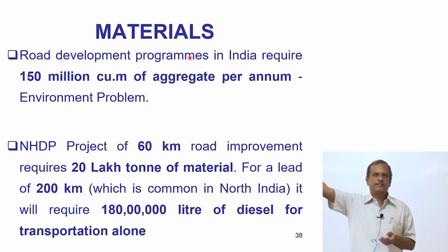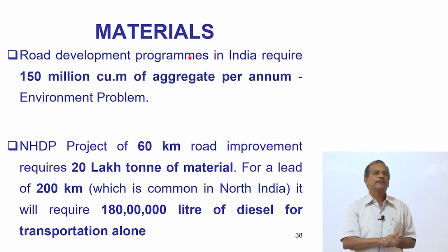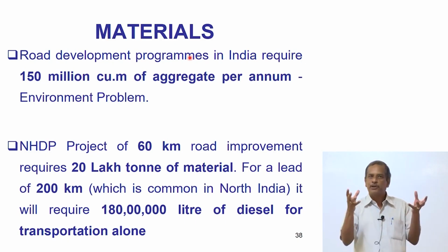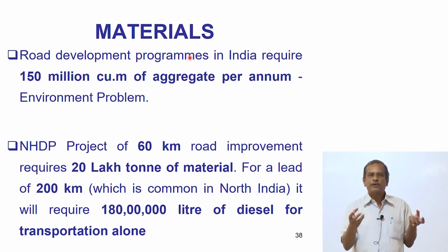If you go to the Northeast, you will not get good quality aggregates at all for road construction. If you go to the Andaman and Nicobar Islands, all the aggregates there will absorb moisture. The water absorption may be more than 2%; we permit up to 2%. If it absorbs more water, it will lose its load carrying capacity. If it is used for bituminous construction, the binder will strip off from the aggregates. So you will find potholes, cracks and rutting failures.